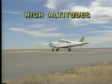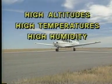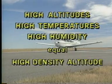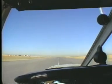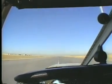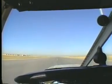Remember that high altitudes, high temperatures, and high humidity all equal a high density altitude. Most modern performance charts have the density altitude computations built into them. But before we look at some of these performance charts, let's consider a few other factors which influence performance.